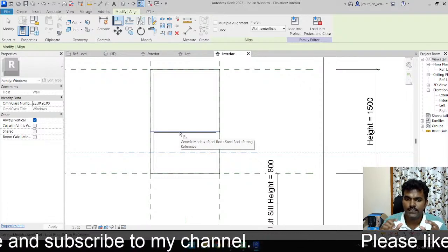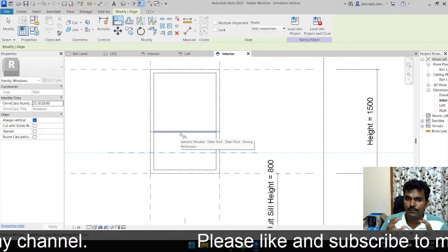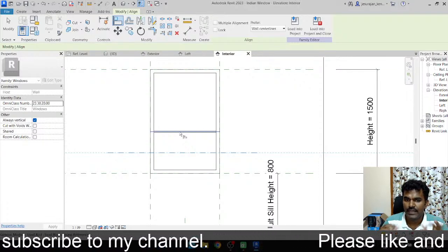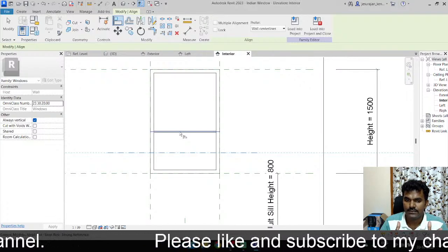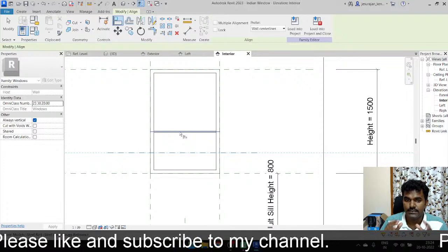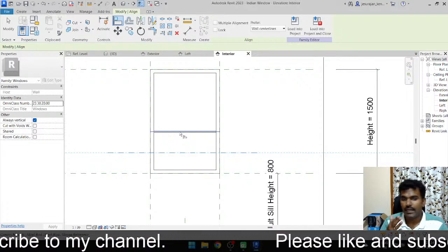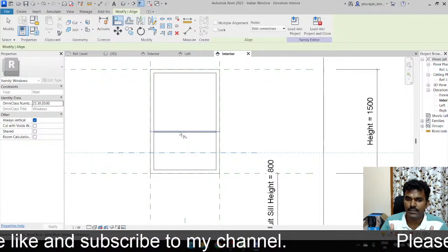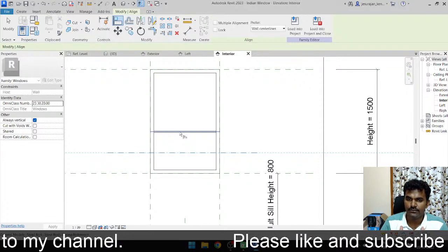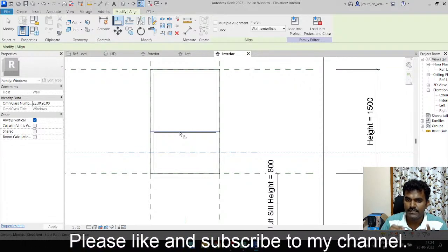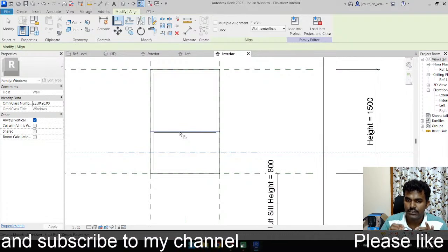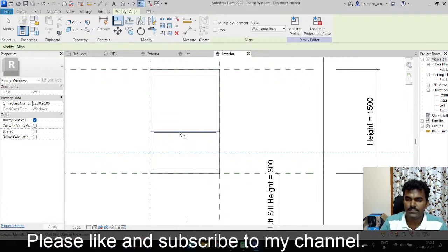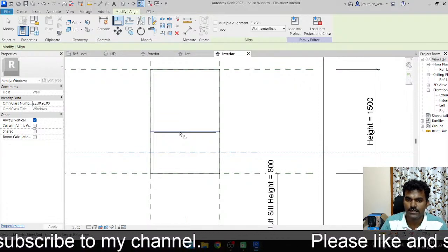So what are you learning here? If you are making the reference plane as not a reference, at that time you cannot align it with the other reference line. So if you are keeping the reference as strong reference, that means you can align the reference line with other reference lines. For example, you are creating a family and you are trying to give a dimension from the center line. At that time you have to keep the center line reference plane as strong reference plane. Otherwise you cannot take the reference plane as a witness line. You cannot take that as a reference for a dimension.